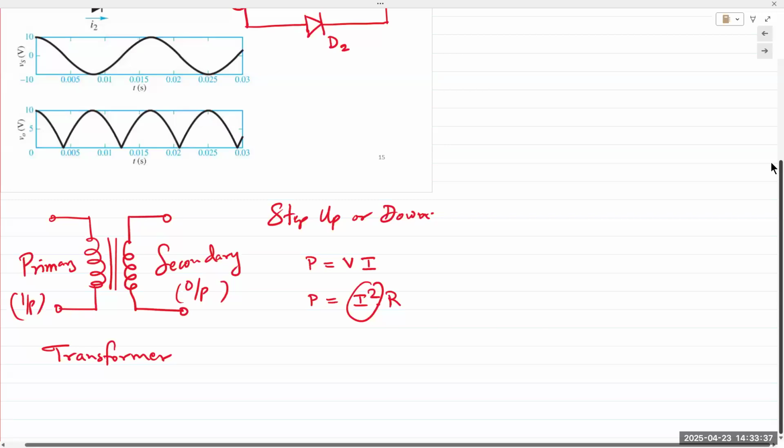Energy is transferred from the power outlet to the charging mat inductive coil. From there, it goes to the magnetic field. Then it goes into your smartphone, and the coil inside your smartphone converts it into electrical energy. That charges the battery. And that's why if you have a thick case on it, it's not going to work, because the thickness or the distance between the magnetic fields will prevent the two magnetic fields from linking up. And if it doesn't link up, energy is not going to be transferred. It needs to link up. Also, if you don't place it correctly right on top, it's again not going to link up.